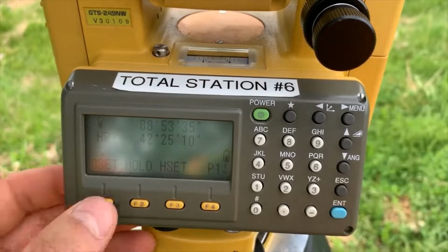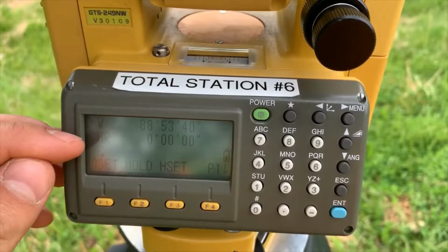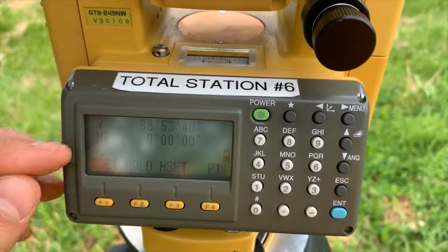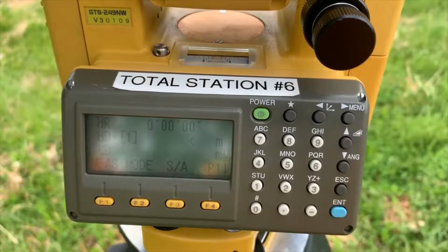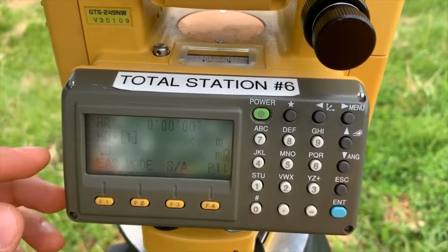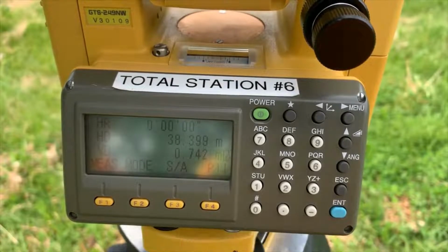So we go to angle mode, F1 for zero set, push yes, and again, our horizontal rotation is now at 0, and we want to take a distance measurement. So we go to our distance mode, and it automatically takes a measurement. So we can see our horizontal distance is 38.399, and you can record that in your sheet for the distance from D to C.